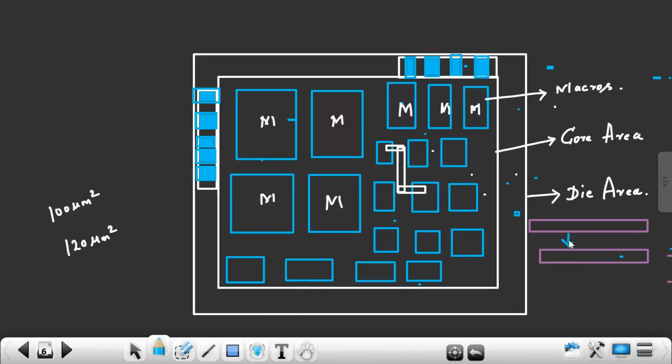If spacing reduces below this, then a DRC rule is violated. There should also be a minimum metal width for a metal layer. And minimum area for any object to be fabricated; if the area is less than that, the object cannot be fabricated. So you have rules like minimum spacing, minimum width, minimum area.